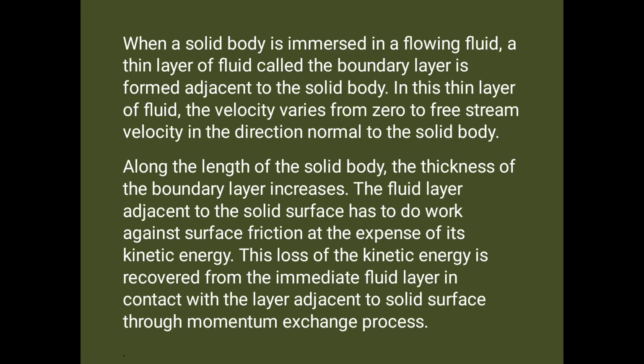Today we are going to see about separation of boundary layer. When a solid body is immersed in a flowing fluid, a thin layer of fluid called the boundary layer is formed adjacent to the solid body. In this thin layer of fluid, the velocity varies from 0 to the free stream velocity in the direction normal to the solid body. Along the length of the solid body, the boundary layer thickness increases.